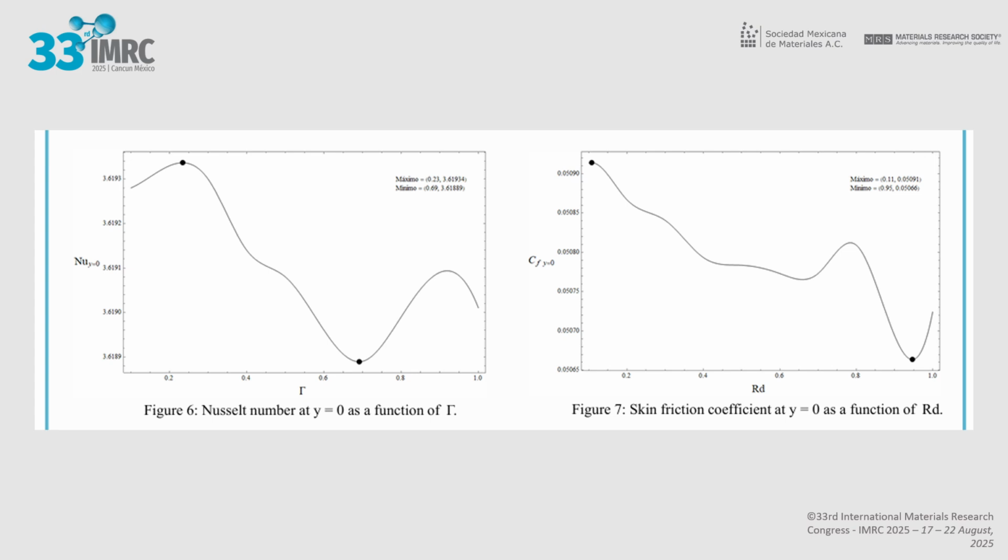However, the coupling between velocity, temperature profile, and heat flux near the wall can induce regions of nonlinear behavior, generating small fluctuations in the temperature gradient, which is precisely what defines the value of the Nusselt number. Furthermore, it is possible that the shooting method used to solve this system is capturing micro variations in the thermal gradient with high precision, resulting in slight jumps in the curve.